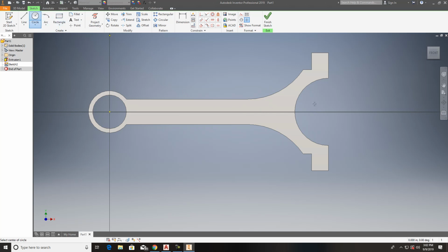So first, I'll find my center point here by clicking on this, and it should catch me the center point. See how the center point comes up? I'll come over to it. I'll grab it, and I'll actually go past it this time, 1.25. And it needs to be double for the diameter, 2.5. So we got that on there, and we'll just go from there to there, and another line from there to there,